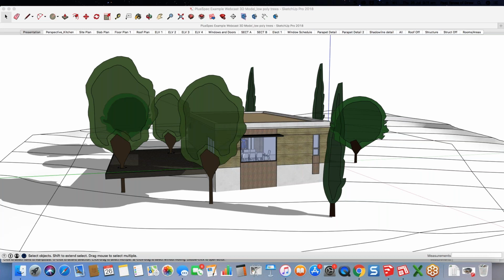It's typically what you report and include in your 2D documentation to tell the exact real level height of items based off the datum. However, some people, when they're doing the 2D drawings, will use finished floor levels or structural floor levels and so forth. So there are a few different ways that you can record height information, and sometimes you use RL and finished floor level.